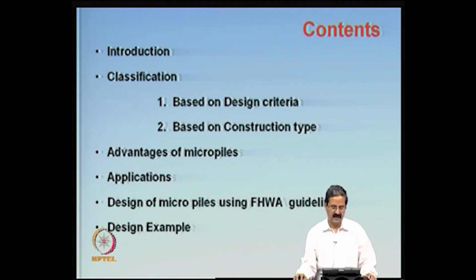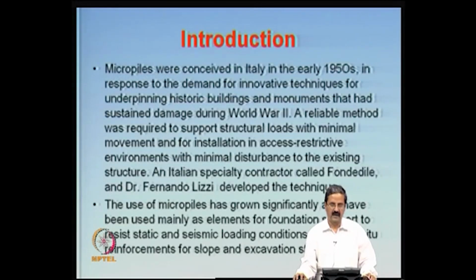The use is that they are very useful in many ground improvement problems, and we know the difference between a big pile and a small pile, in the sense that you try to design a diameter for the load. Here we are trying to replace that bigger diameter with a small number of piles, and